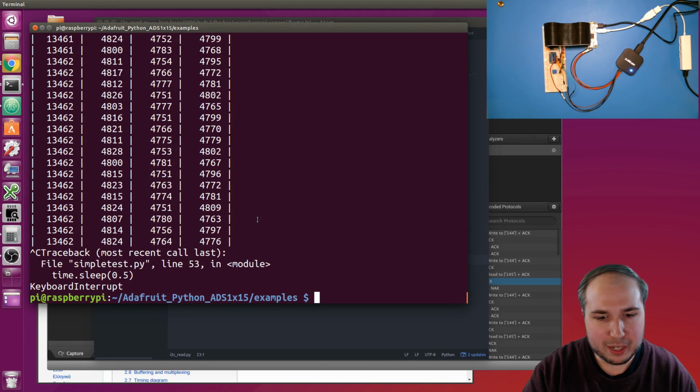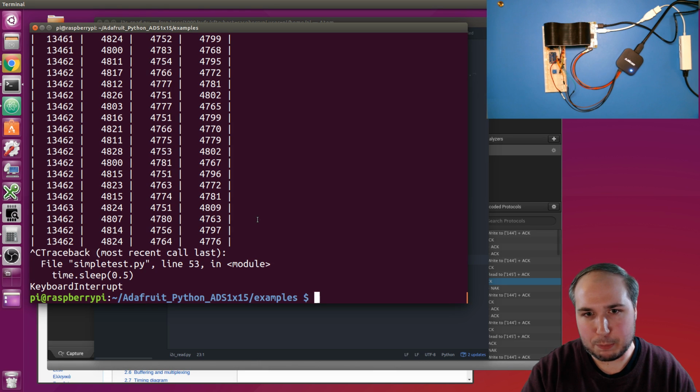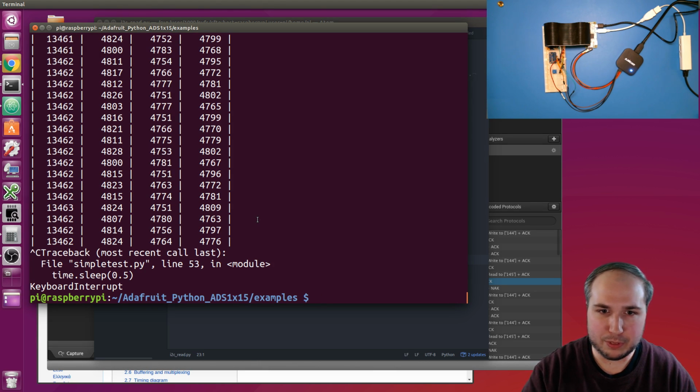And maybe before I dive too much into the code, I think I'd shown this before, but there are some interesting tools in Linux that let you look at the I2C bus and see what devices are there, because we saw earlier it's a bus where each device has an address assigned to it, and it turns out there are some neat ways that you can query the entire bus to see how many devices and what devices are there.